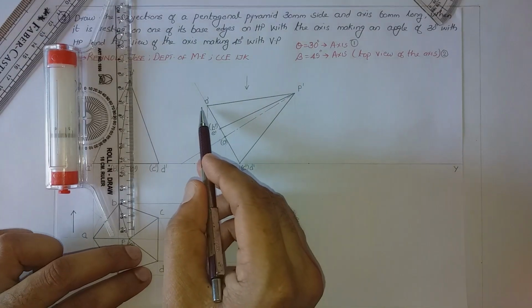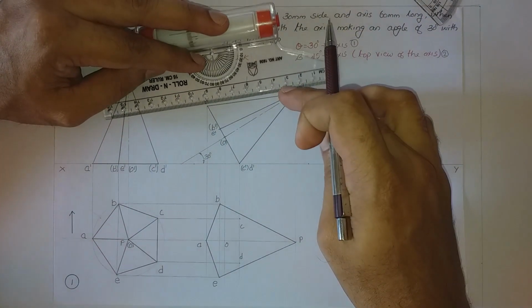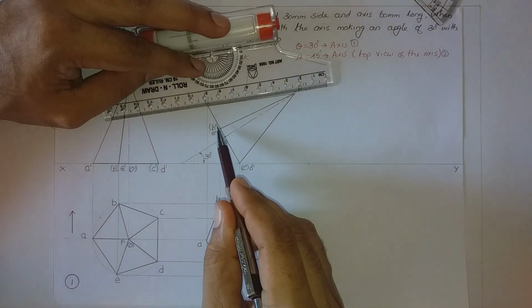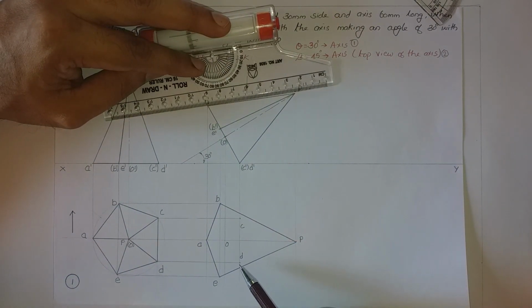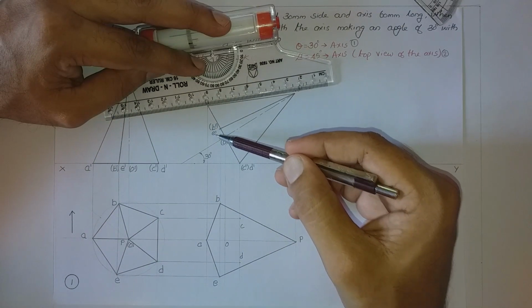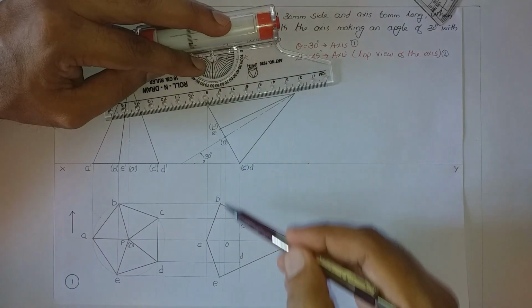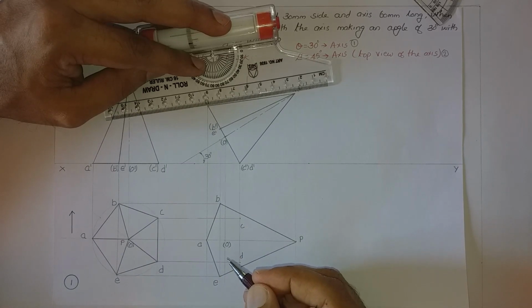So we are having a line connecting B dash and A dash. Below this line and between the XY line, we have got C dash, D dash, O dash, B dash, and E dash. All these points may be invisible in the top view if they are not a part of the outline. We shall check it one by one. B and E are a part of the outline, so they are not invisible. O is the center of the base. It is not a corner. So O is invisible, but as it is not a corner, we won't be having invisible edges from point O.